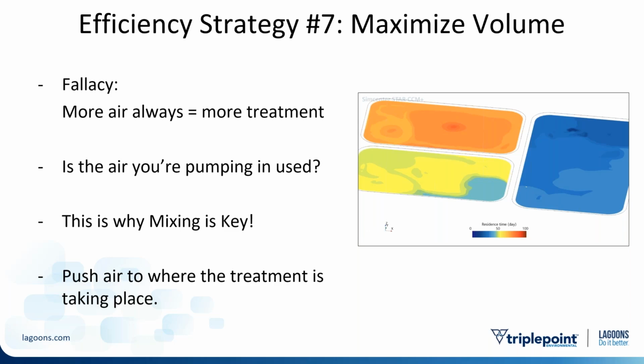So having a thoroughly mixed lagoon system, making sure that the air and the waste are always in contact, is very important. So mixing is absolutely key, and we want to make sure to put the air where the actual treatment is taking place.